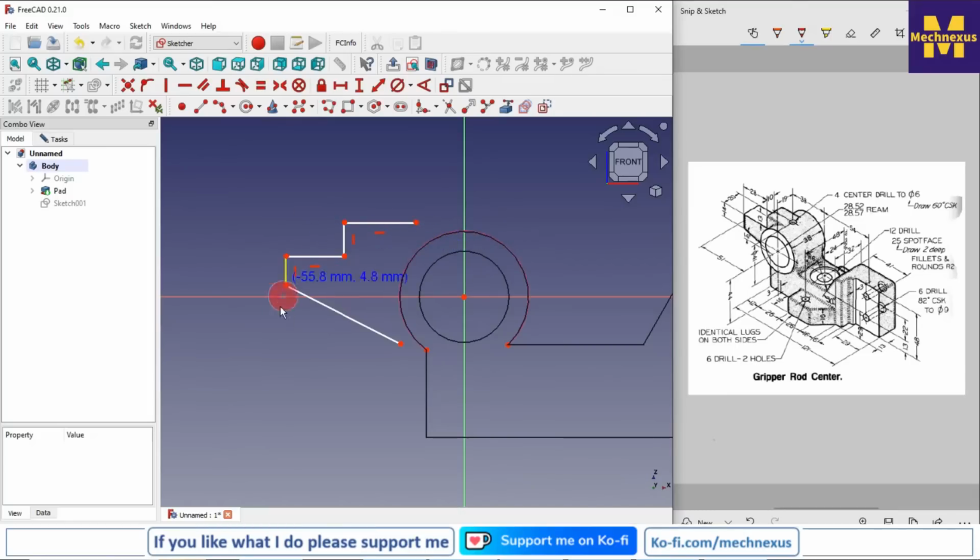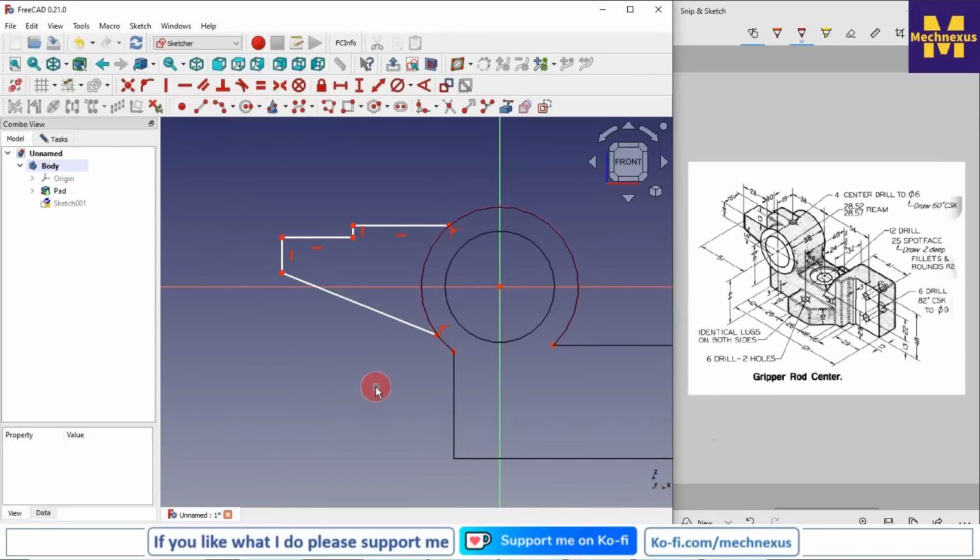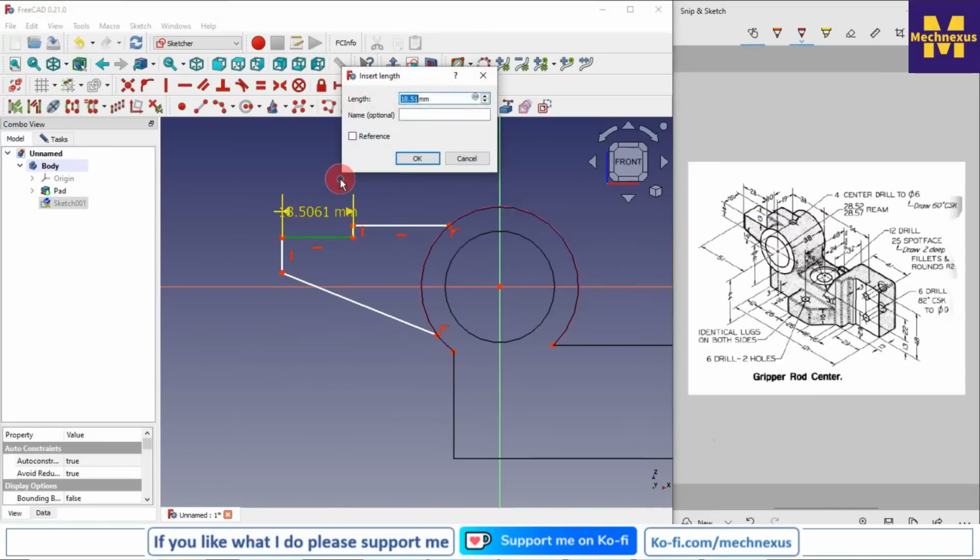So we have created the rough sketch. Now we will constrain it. We will select this point and this arc, constrain it, this point and this arc, constrain it, and now we will give the dimensions. So if you see the drawings, this is the 28. So I will select this and give my dimension 28.